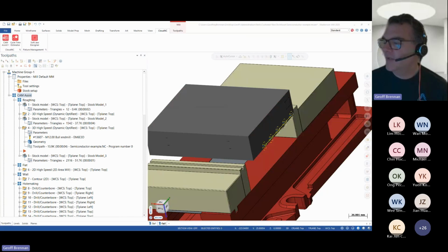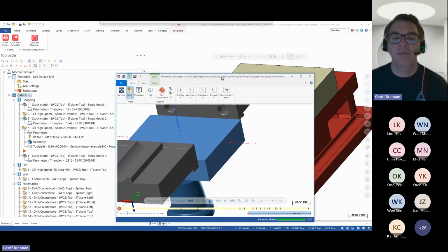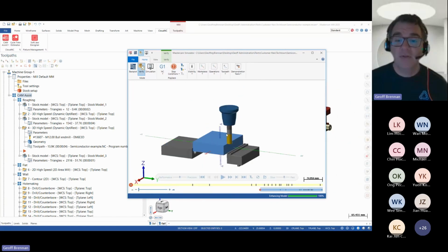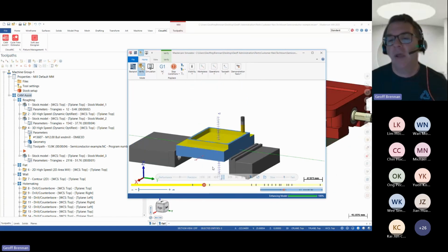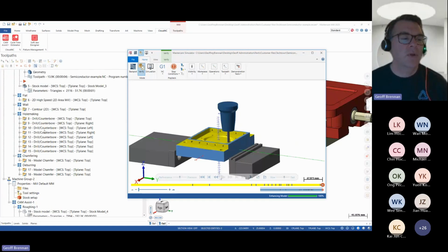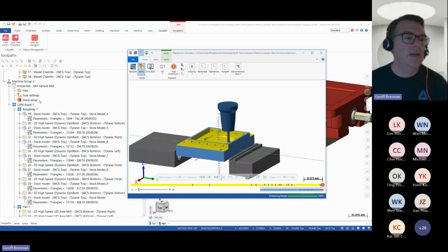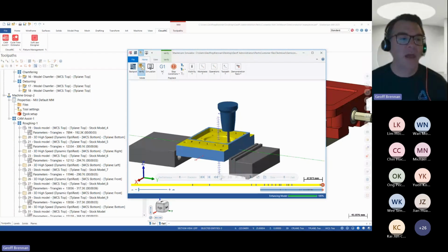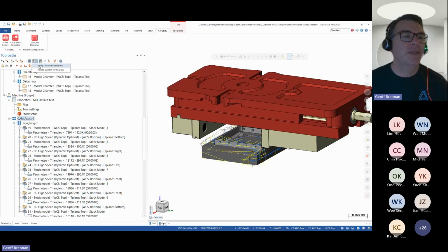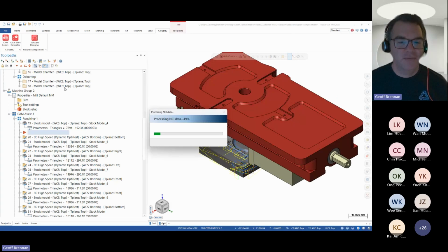So one of the questions we get quite often is, does CAM Assist require any special post processors or anything like that? So when it comes to 3+2 operations, the sending out to the post is going to be dependent on, of course, your setup and what you have in your own post processors. But we basically are generating Mastercam toolpaths. We're not generating G code directly. So working with your post processor vendor, it should work entirely with what you have already. There are, of course, edge cases where things happen, but those are very, very few and far between.